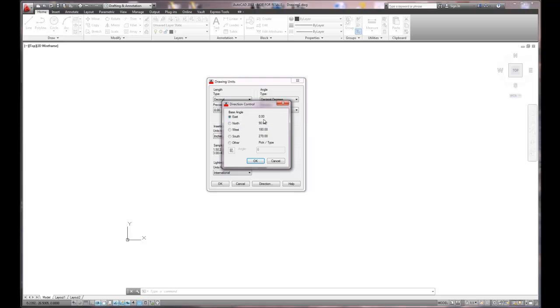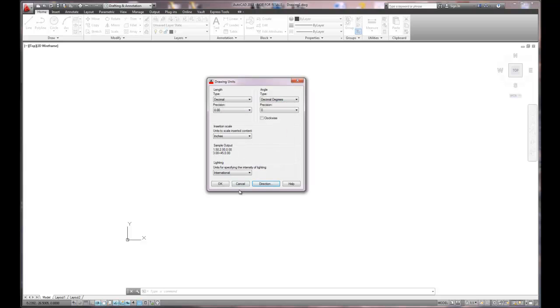Right now, east is 0, which is, when you look on the magic compass, 0, 90, 180, 270. East on the right hand side being 0 is mathematical based. We can also have 0 as north, which would be map based, right? North being 0 degrees for maps, flying, boating. But in drawing and mechanical and architectural styles, 0 is to the east location. Again, no changes. We change the decimal place to 2 decimal places.